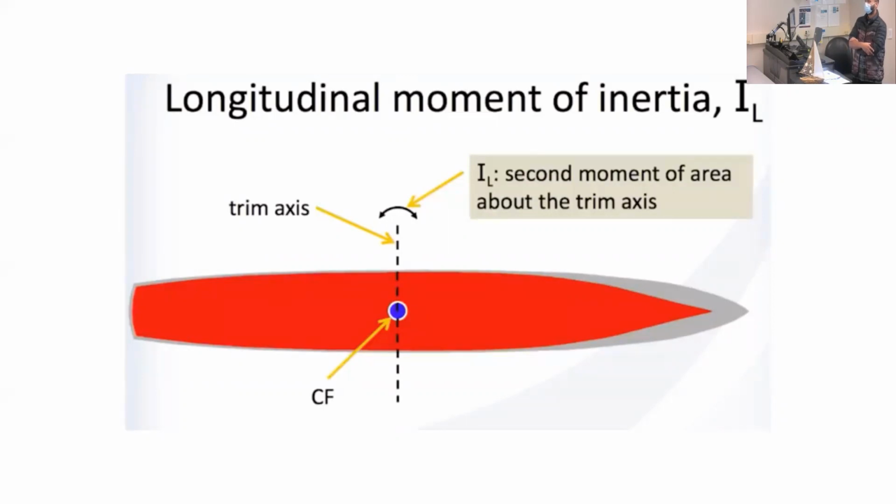That's related to a disk. Do you remember bh cubed over 12 or l cubed over 3? For very simple shapes, the value is straightforward, like the area of a rectangle, L times W. But for a potato, it's not the same. The area is not straightforward to compute. You have to do numerical integration. Same thing here: for moment of inertia, you do numerical integration.